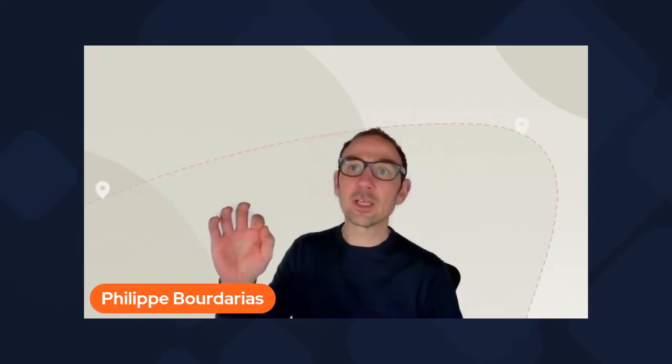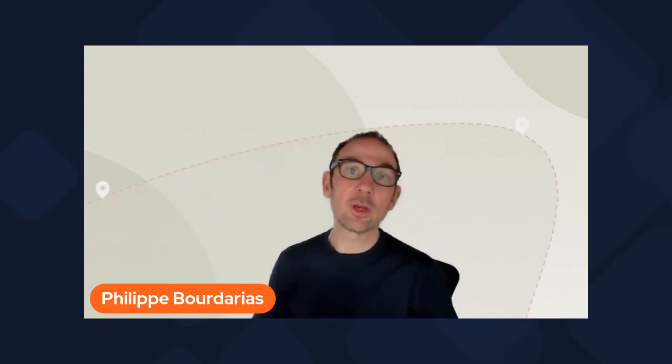Yeah, so, Andy, I'll try to answer your question. If I don't, please reach out to me and we can discuss it over the phone or in a Zoom meeting. When you create a route manually, it's very easy, as you say, to stop it at the wrong point. But when you double click on it, a lot of small points appear on the route, and you just take the last point and continue plotting the route the way you did before.